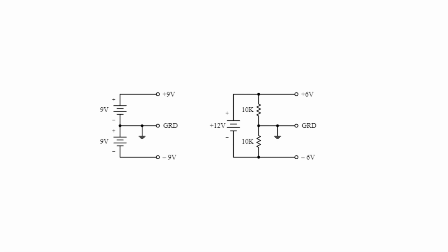These devices will clip the output if the inputs attempt to go negative, making them unsuitable for AC coupled applications. To avoid clipping while still using a single supply, it's possible to take a conventional op-amp and apply a DC level to one of the inputs using a voltage divider network. This in turn provides a DC offset level at the output. With the input offset voltage in place, when an input signal goes negative, the voltage applied to the input of the op-amp will dip below the offset but will not go below ground. The output in turn will fluctuate about this offset level, though to allow for input and output coupling, input and output capacitors would be needed.